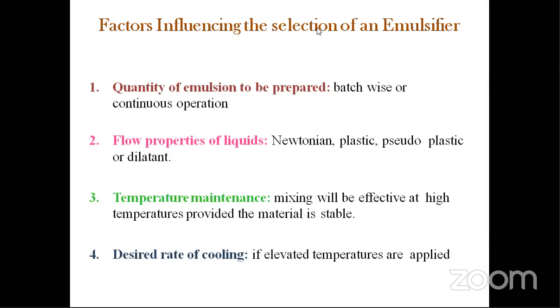That is called deformation. Okay, that type of phenomenon also happens with viscous liquid or plastic flow. The deformation is caused by the stressing of a material beyond its elastic limits. If it crosses the elastic limit, the deformation or the new shape remains. When the stress is removed, it does not come back to its own nature. So it is called plastic flow.